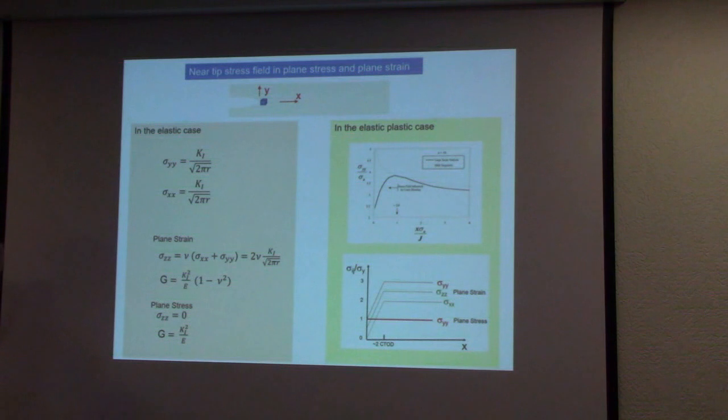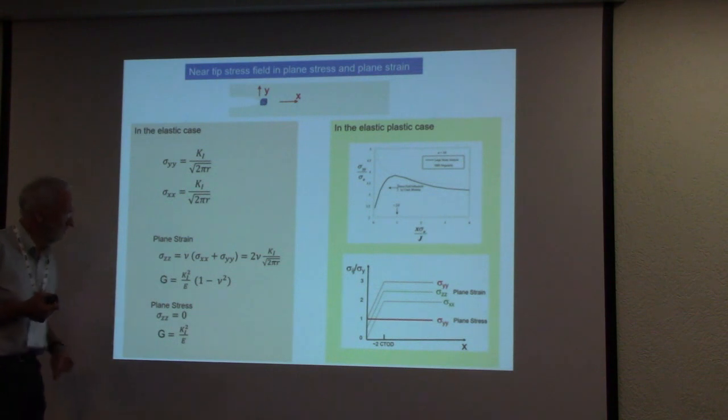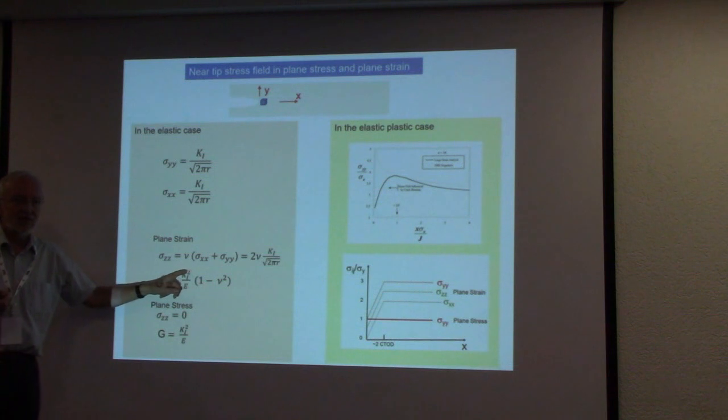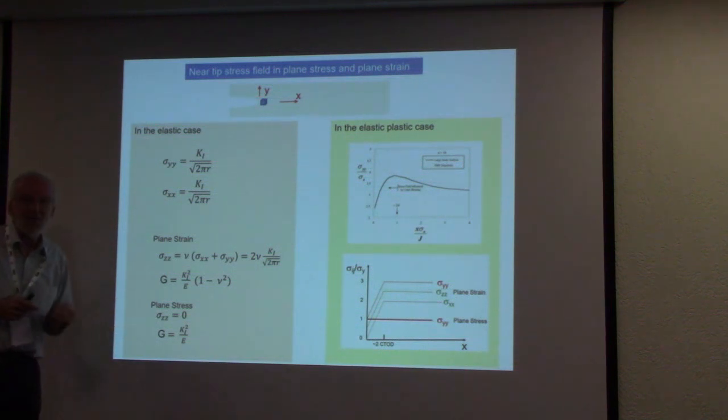And there is one difference also between plane stress and plane strain. If we recalculate the energy release rate, there is this small difference: in the plane strain case, the energy release rate is somewhat smaller than the energy release rate in the plane stress case.